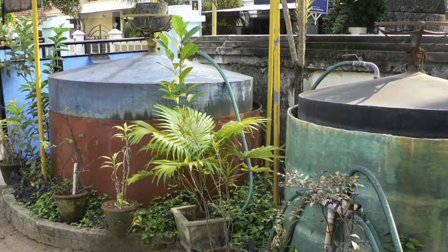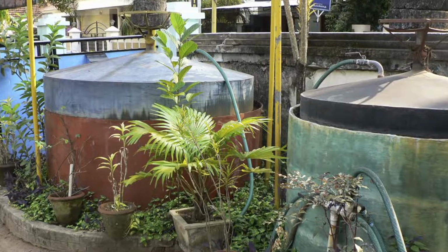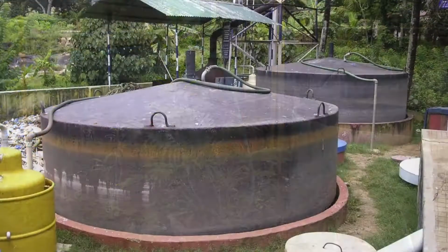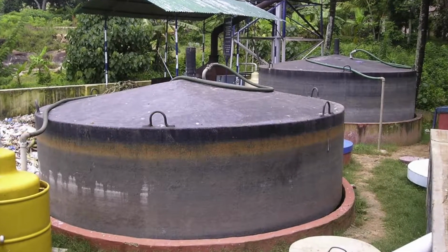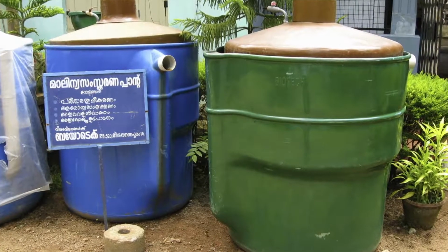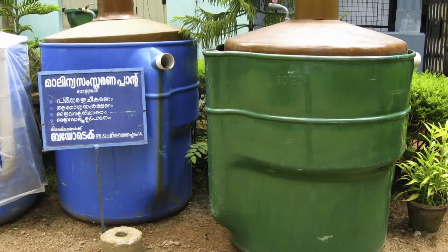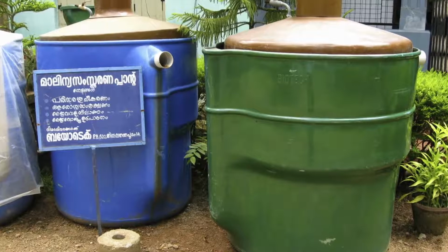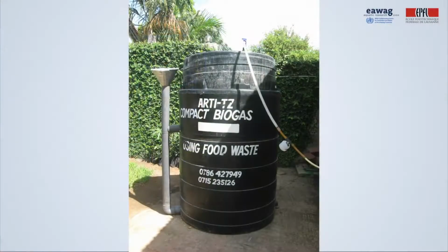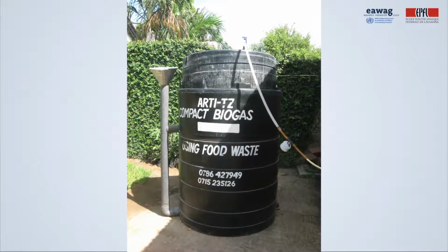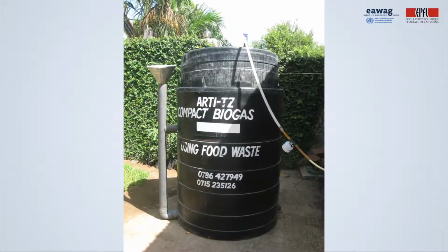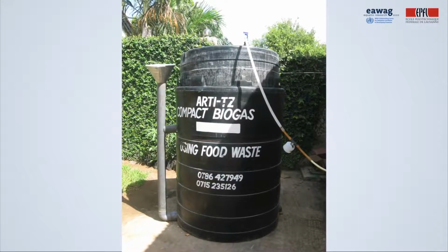Here is an example of such floating drum digesters from India, with the metal floating gas holders. Or here another, also from India. Here are examples of small household units made out of fiberglass reinforced plastic. The brown part on the top is the floating drum. Or here another example from Tanzania, made by using the typical water tanks out of plastic and some plastic piping.